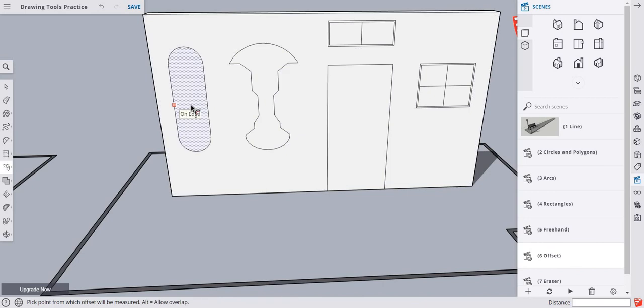We're going to, you actually click on the surface. So by doing this, it's going to reference that red dot right there. So I click on the surface, I drag the particular offset that I want, and you can go inside or you can go outside the shape, and then you click again to finish it. The offset automatically will delete the geometry as it comes inside and starts to crash in on itself. So you can see as we're bringing in this kind of unusual shape, as I pull in, it's going to smash into itself. It actually deletes the overlapping geometry.